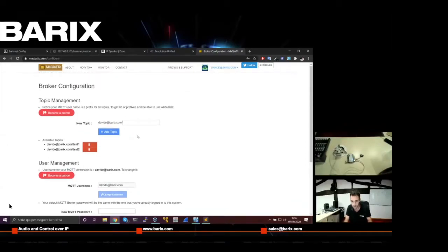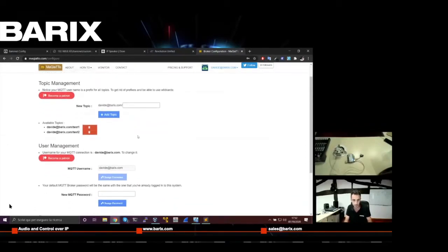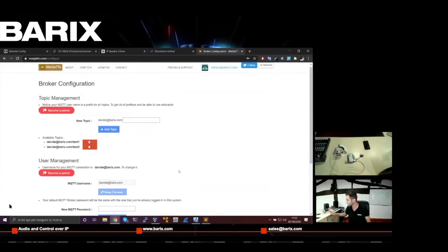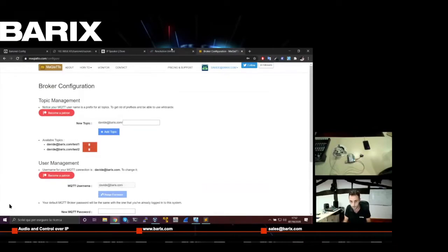It took me like 10 to 15 minutes to have my account created. I created 2 topics where the devices are subscribing to. So both my client on my phone and my Barionet are subscribing, in this moment, to this topic right here. So whenever I press that button, the relay will be closed.